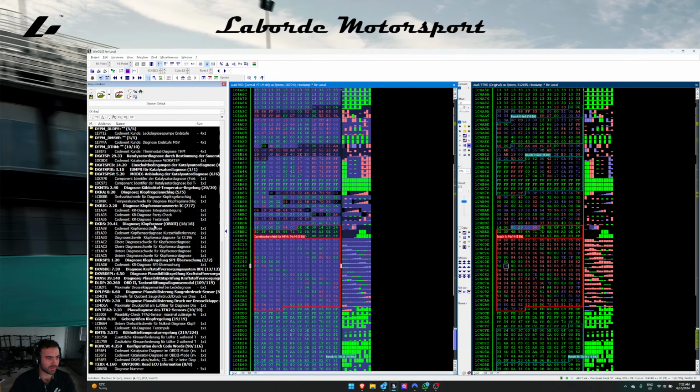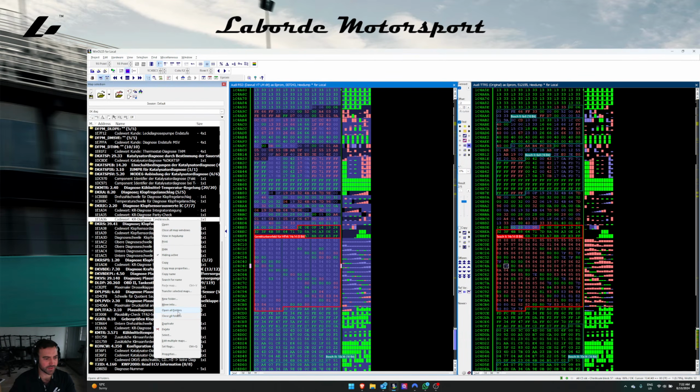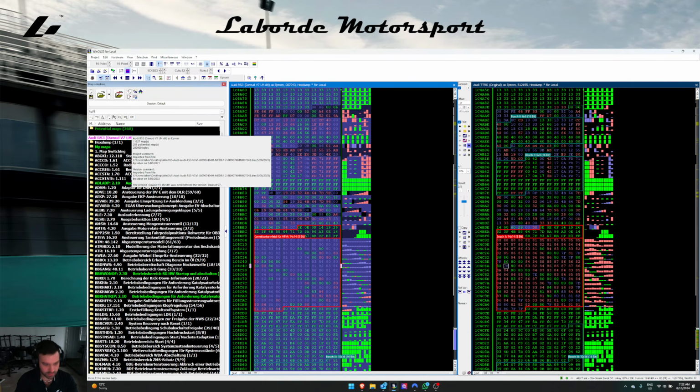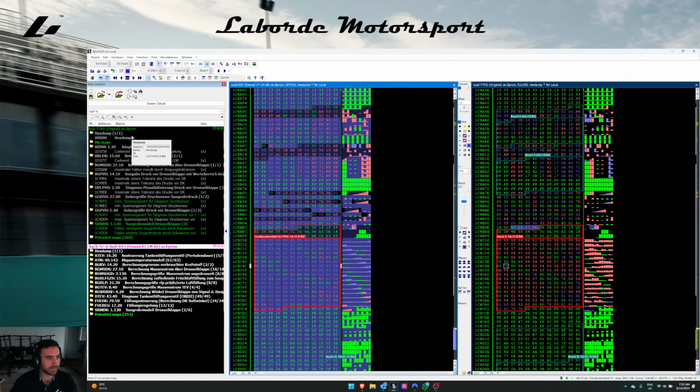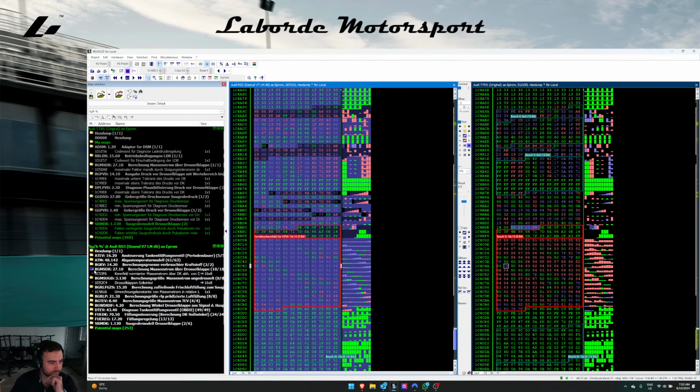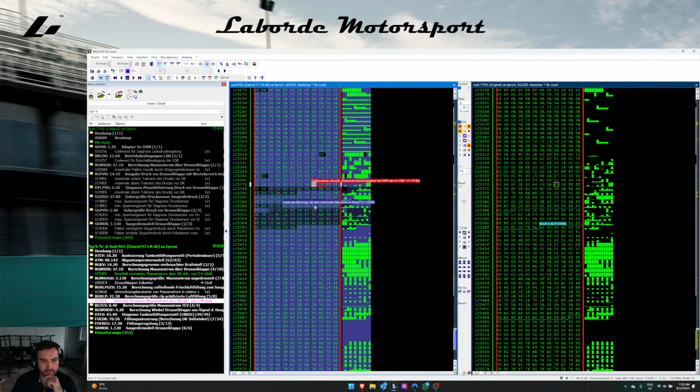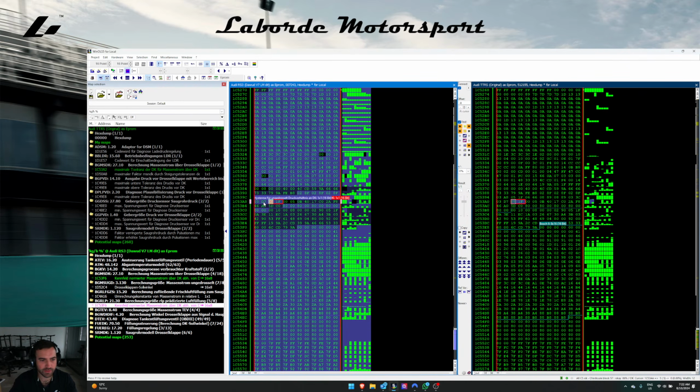I know that with a lot of Bosch software versions, the maps that we need to tune are near the airflow map for the throttle plate and also the throttle plate itself. So if I go ahead and search left and right here, usually they'll be around here somewhere. Yeah, see, maximum tolerance for mass airflow. Sometimes there'll be some other ones too which we need.